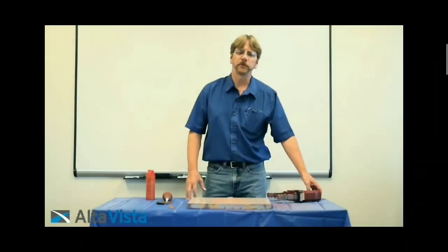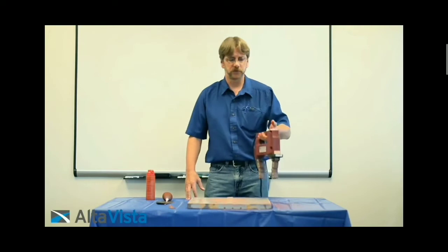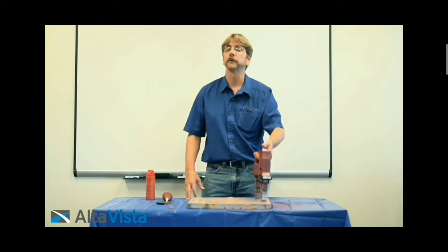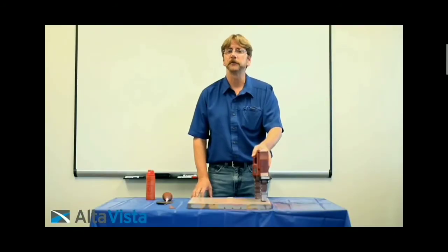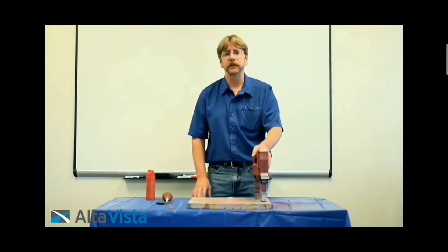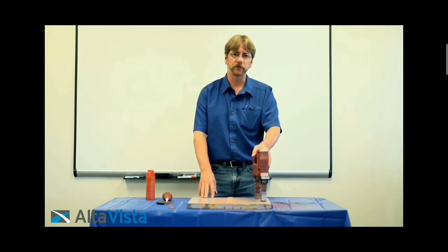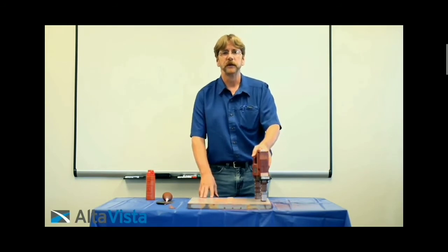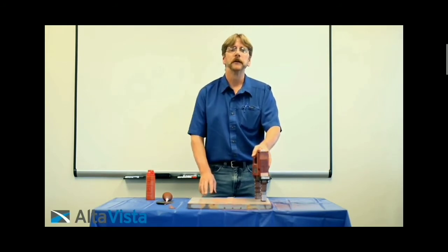So what we're going to do is demonstrate the proper technique to perform magnetic particle testing through a layer of paint on a component. ASTM E709, the American Society for Testing and Materials standard that we're working to, doesn't allow you to test through paint. You need to test through uncoated surfaces. You're allowed 1 or 2 mils of paint, and then that would be acceptable.